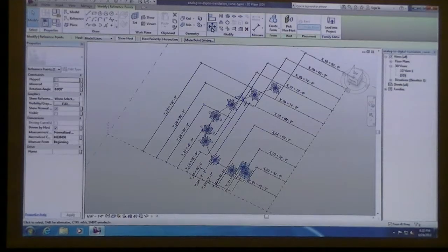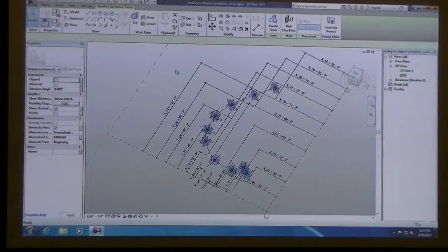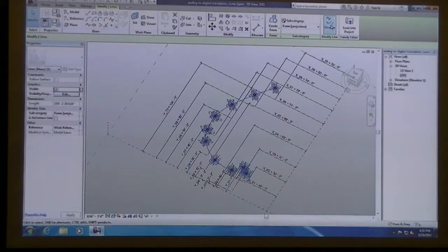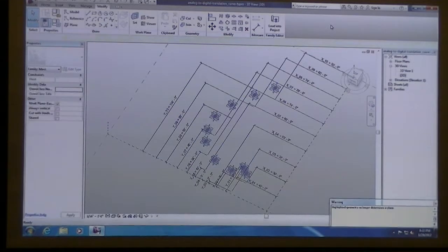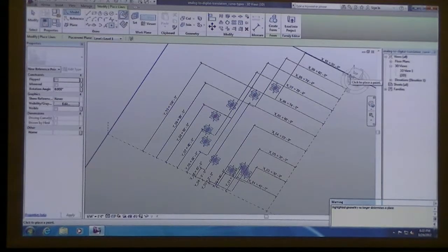I don't know if we can move this one. Yeah, that. So it's not going to allow you to just add in a point. So what you'd have to do is click on it and hit the dissolve button. That will take away the curve but maintain all of your properties and all of your points. And then you could set up your other points that you need to add in and the additional properties that you're going to need. And then do the spline through points again.